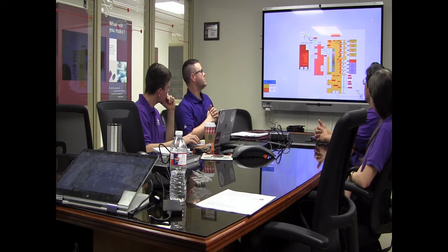Most of our sensors are on the BoosterPack sensors pack, so we're using 2 main sensors on that board, so only 2 are listed here. It has additional sensors that we don't use, but we're using the OPT3001 ambient light sensor and the BME280 humidity, barometric pressure, and temperature sensor using I2C, so we speak to both of them using the same address.